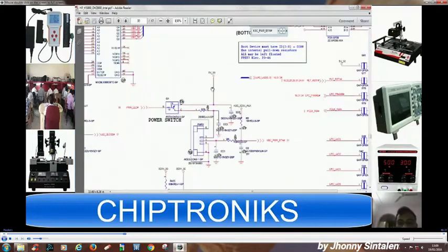And you can see over here the arrow is from emitter to base, so it is PNP. And what happens in PNP? The current would flow from emitter to collector when the base is connected to the ground, right? And you can see the base is connected to the power LED signal. So if this signal becomes active, 0 volt would come over here, and then this transistor would work and the power LED will glow. But this power LED will glow only when 5V_S3 comes.